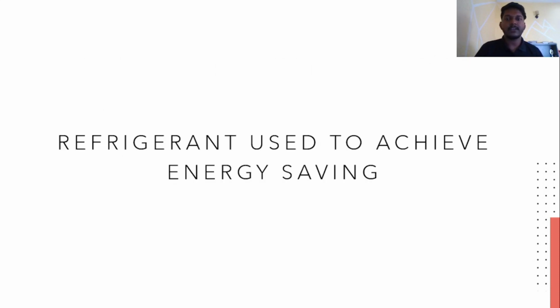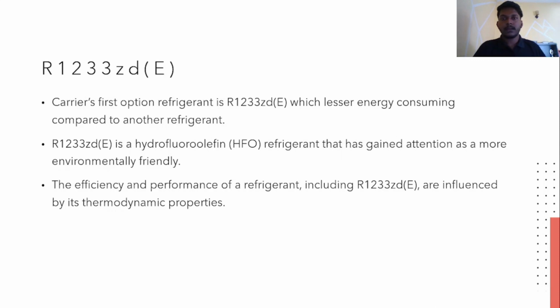Okay, so next is refrigerant used to achieve energy saving. In Carrier, R1233ZDE is the most compatible refrigerant, because Carrier's first option refrigerant is R1233ZDE, which is lesser energy consuming compared to other refrigerants. R1233ZDE is a hydrofluoroolefin HFO refrigerant that has gained attention as more environmentally friendly.